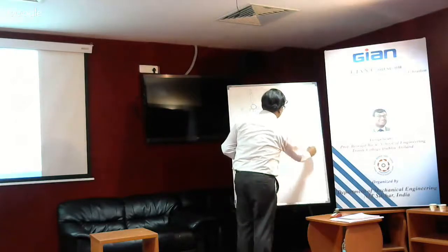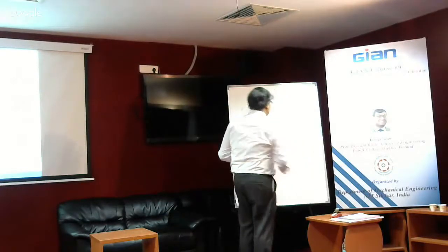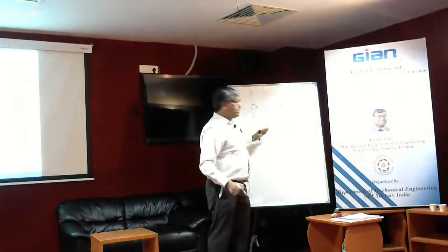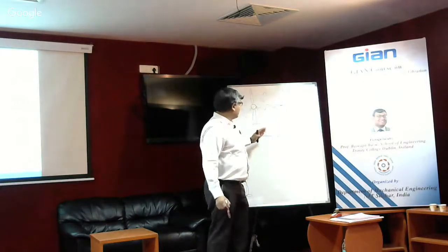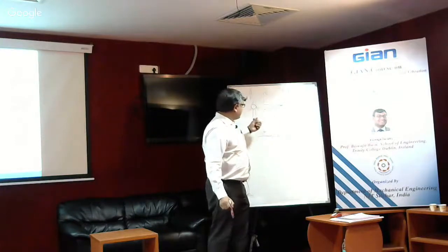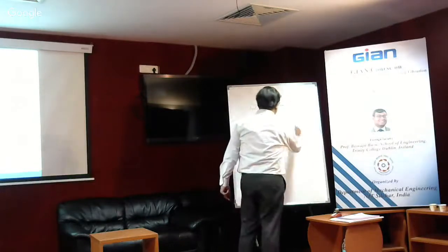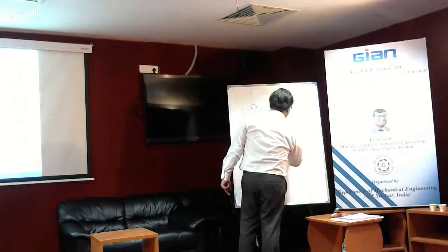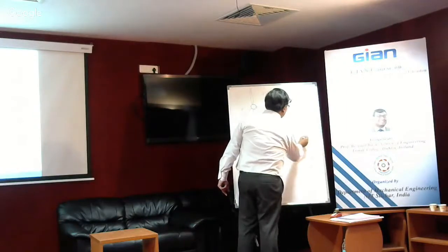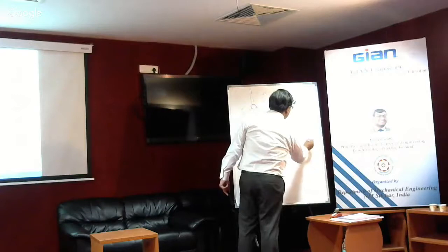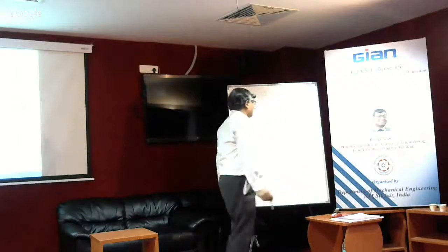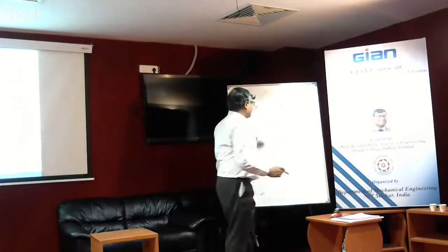Here there is no separation, that's fine. But on the top, the flow comes in, hits this nose of the airfoil, and then tries to follow this, but then at some point gets detached. So meaning that there is actually a region over here where this detachment of flow happens.